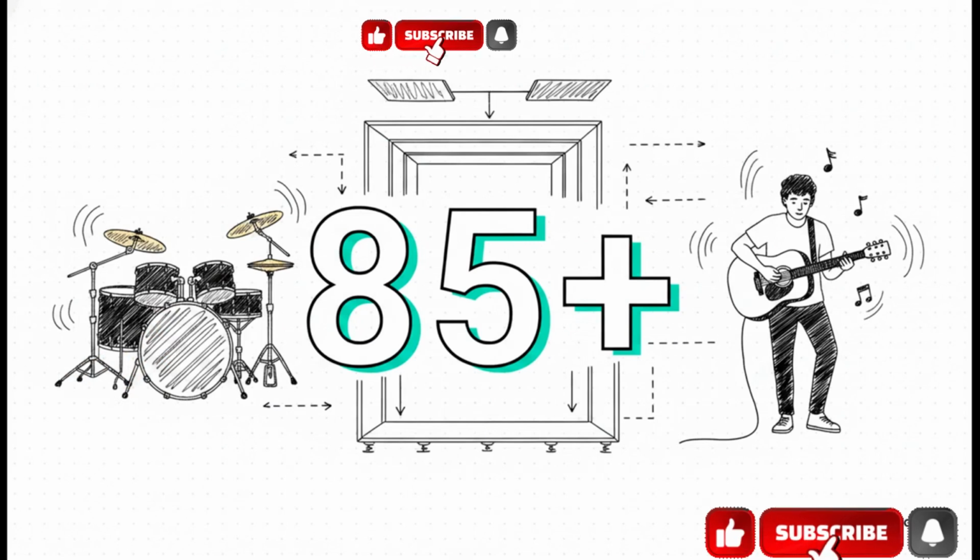But what if you were building a professional recording studio, right? A space where you're recording high-energy drums right next to a room where someone is mixing delicate acoustic guitars. You need an STC rating of 70 to 85 plus. No way you're getting that with standard materials. This elite level of isolation requires highly specialized room-within-room construction. We're talking heavy, decoupled layers where sound vibrations literally have no structural path to travel along.